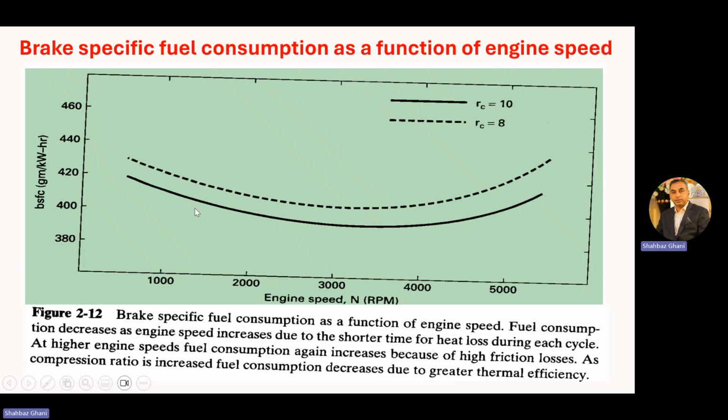As the speed increases, the brake specific fuel consumption decreases up to a certain point. When the speed increases further, it also increases. With a lower compression ratio, we have this graph.